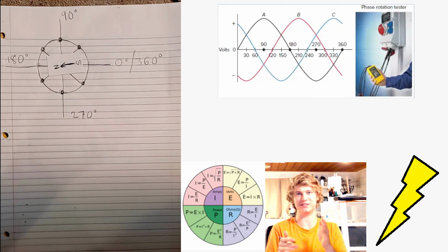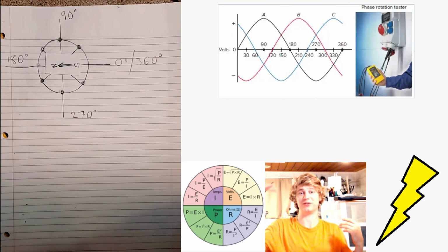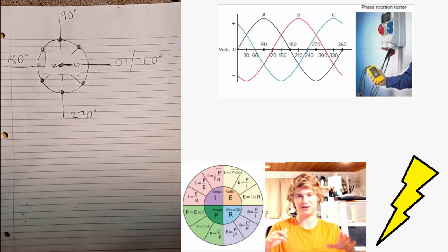But okay, above you can see at 120 electrical degrees, that is where each of the phases starts. So at 0, you see phase A starting, 120 degrees, you see phase B, 240, you see phase C. Okay, and because they're 120 electrical degrees apart, we can see that when phase A goes to 180 degrees back down at the 0 crossing, we can see above it, phase B is not quite at its peak, and it's not in the middle of the 0 crossing and the peak like where it is when the 2 phases intersect, but it's somewhere in the middle of those 2 points.